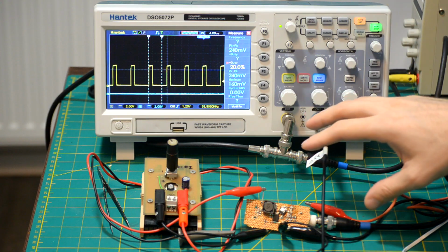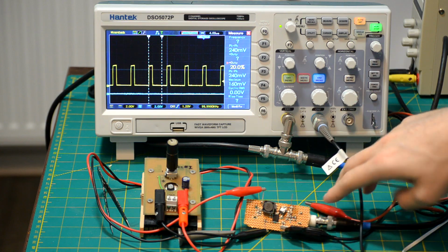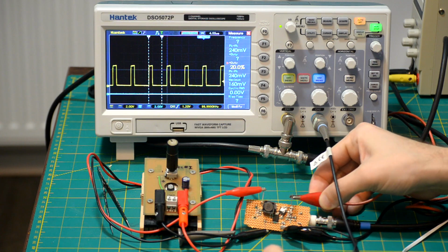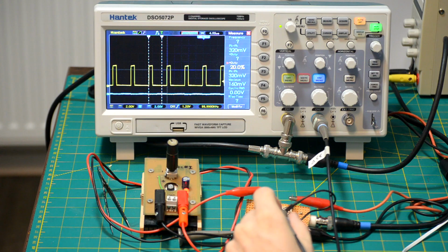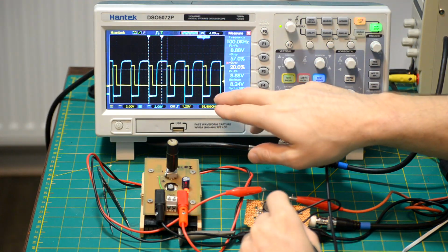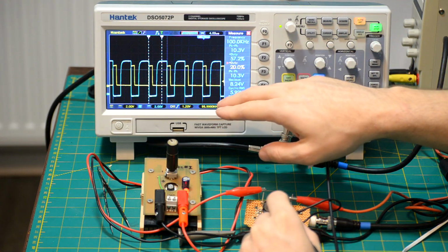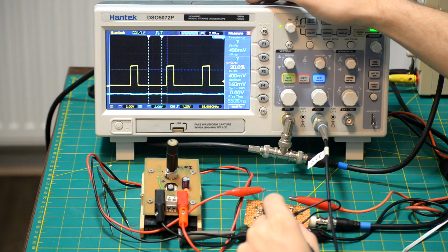So what I got here is the same setup as before, only difference being that I swapped the P channel for an N channel. And if we run this thing, we see that the output is working. And if we look into the switching node, just like we've seen in the simulation, it's switching. Difference being that this time we have an inverted switching node compared to the input signal. That's because we swapped the P channel with the N channel. We still have this slope going on, so the transistor is not turning on very quick. That can be fixed using the push-pull type of driver.